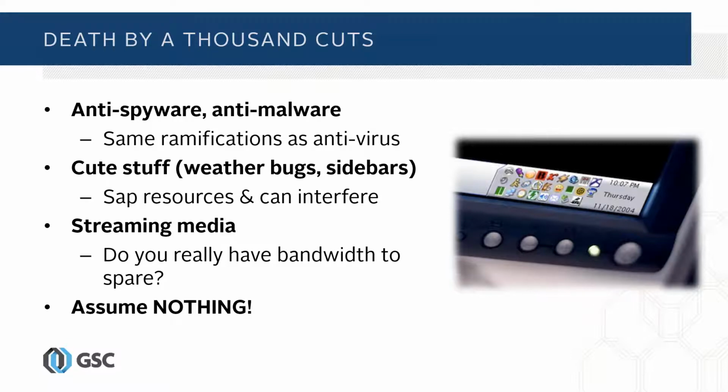So if you want to maximize the performance and stability of SolidWorks, don't have internet radio running or streaming videos and music or whatever on that same machine. Do that on your phone or something like that. Try to keep things as clear and as open as you can, especially on the network, if you're really doing some heavy lifting in SolidWorks and doing some big stuff.